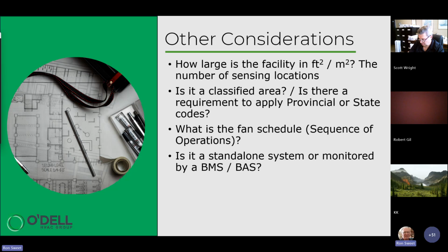Any system can interface to any other system. And I was taking the example of an enclosed parking or underground parking garage, a gas detection system for monitoring vehicle exhaust, carbon monoxide, nitrogen dioxide, interfacing to the fire alarm control panel. It can do that.